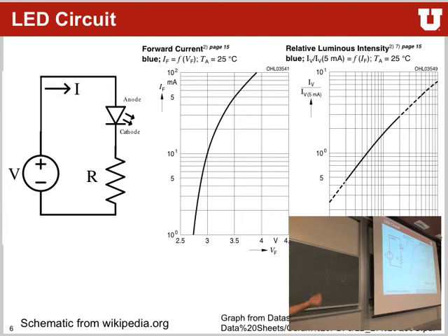So imagine you would do it the other way around, where you take an I/O line, go through the LED, and then out to ground. So now if you pull this line high, you will have current through here. All the current that you're providing through this line has to actually go from the power line into the MCU and back out again. And they're most of the time worse at doing this than at sinking the current.